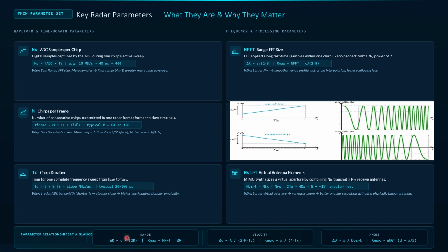Once we are trying to design an automotive radar, there are a few things we have to be clear about. One is what range we want to have, how far the radar can see. That depends on this number of samples, and that is dependent on the ADC frequency. Basically, you are transmitting some sinusoidal wave, for example, and getting something reflected back. You do the mixing, you get the I frequency, and then you need to sample that, from the analog to the digital domain. So that ADC has a frequency. You'll see how all these things are related.